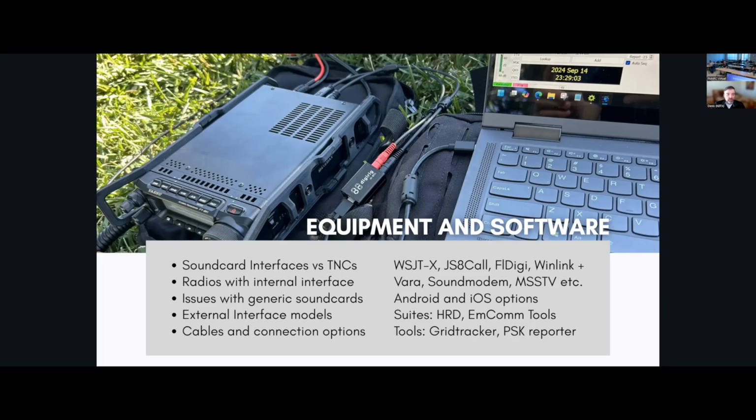One thing worth mentioning is that some of the radios, especially more expensive desktop radios, have the equipment in them. So you will not need to purchase anything additional to operate digital modes. All you need is a USB cable directly between your radio and the computer, and you can run the software.